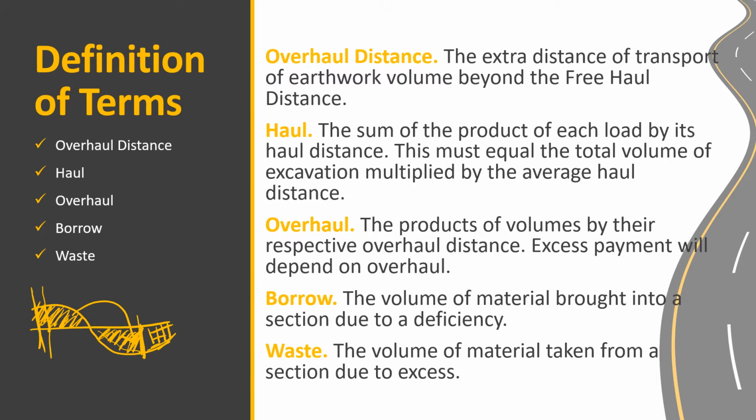So kulang pa ng soil na i-fill dito. So you'll have to borrow from a distance or somewhere na magiging source ng earth material. So yan yung borrow. For example naman, if you have this section, in this part, if the volume na i-fill is hanggang dito lang sa cut, then ito is hindi na siya kailangan. So ito yung magiging waste na material.